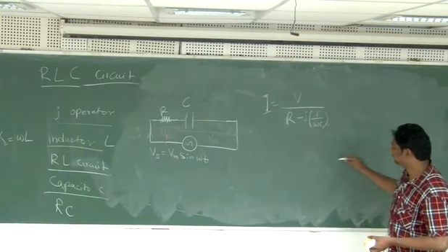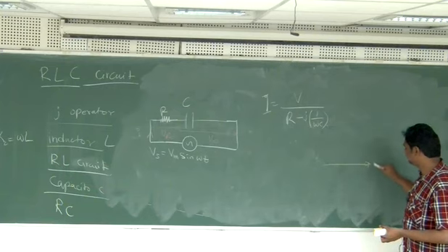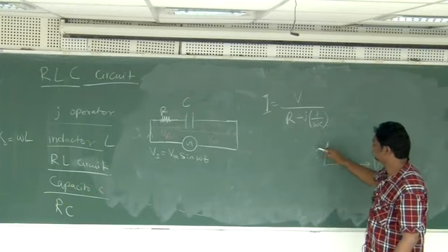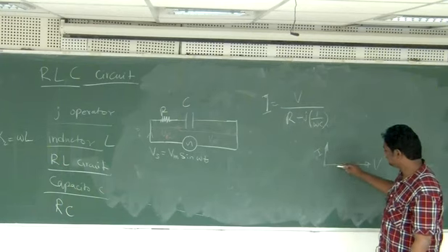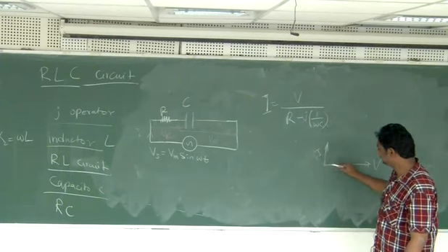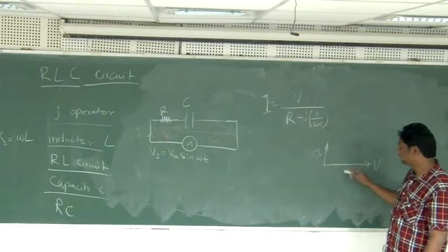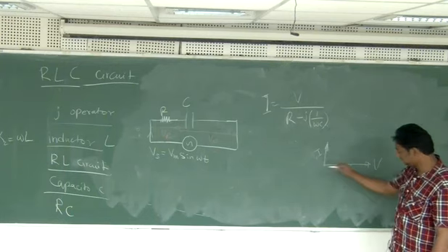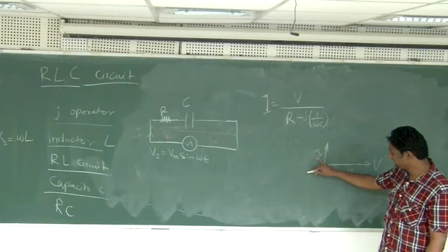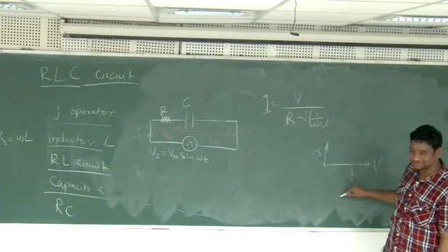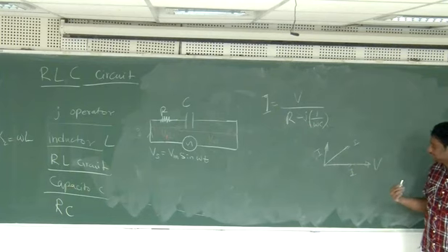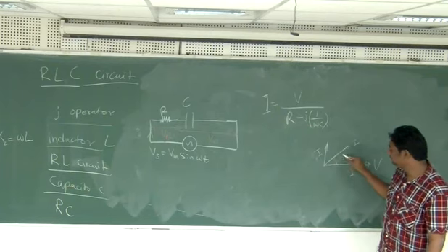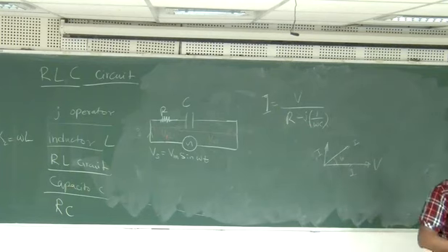So this is voltage and this is current. I for only pure capacitance, I for resistance, and the I will be like this if you have both R and C. This angle will depend on the relative values of R and C.